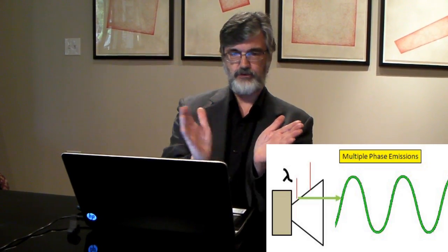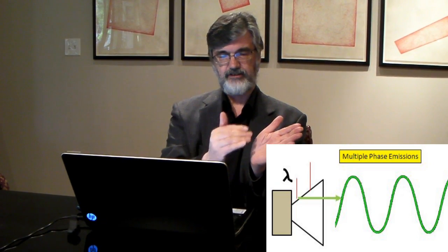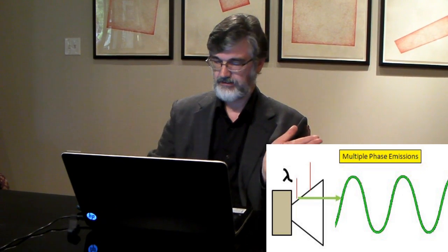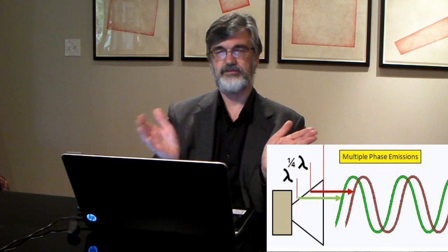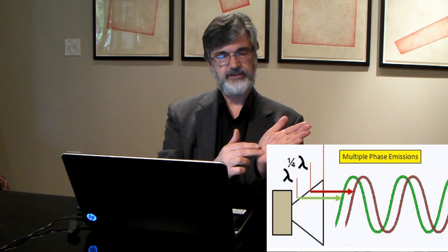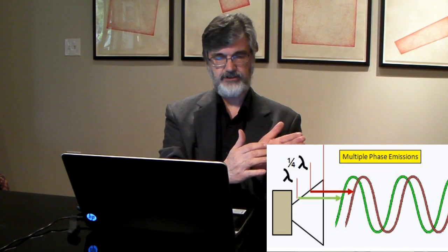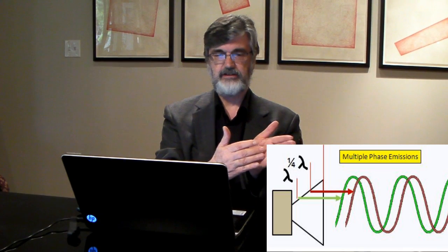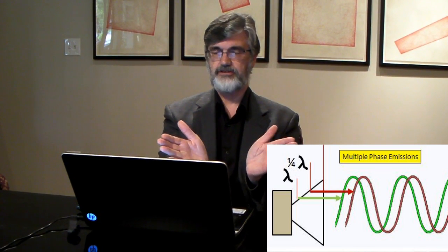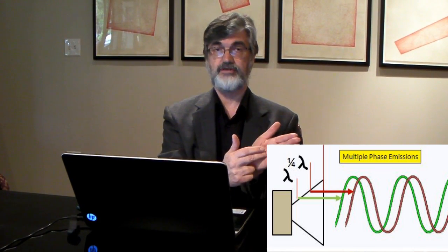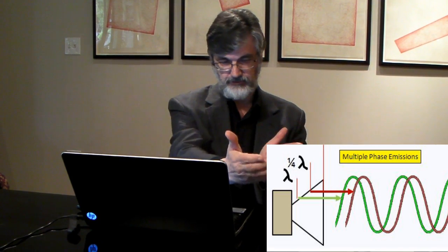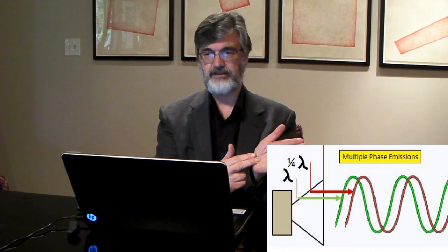If we take a look at emitting the sound that we want, and look at a point on the cone, from here it moves a compression wave forwards as it moves. That's the sound that we want. However, the cone has some depth. So as we progress on to the second slide, we'll see that farther up on the cone it's farther forward, and depending upon the frequency you're trying to produce, that may be a quarter of a wavelength more advanced towards the front than what you were emitting here.